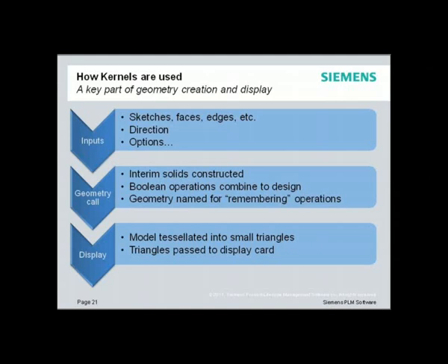You do your sketches, you solve them, and then some solids are constructed, and then comes the display. Well, I think the thing that a lot of people forget or don't realize is that when you edit in the history tree, editing is almost a misnomer. What it does is it rolls back, it undoes everything up to the point of the edit, and then it completely redoes that in order to achieve its goal. And so what that means is that every time you edit a feature, you are completely reconstructing from scratch every feature that is downstream of that.